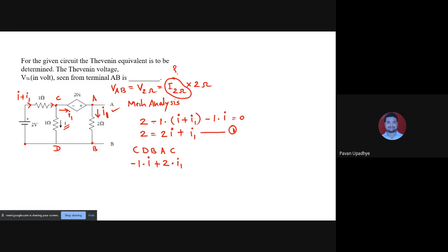I am repeating it. While tracing the circuit from B to A, I was moving from B to A, but current I1 was moving from A to B. So I and current are in opposite direction, so the potential drop should be considered positive.